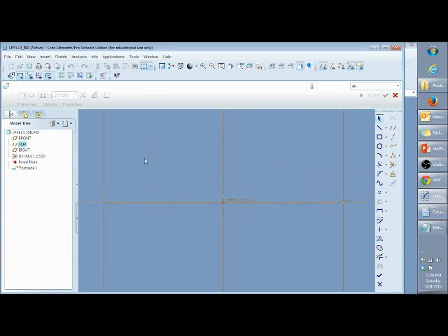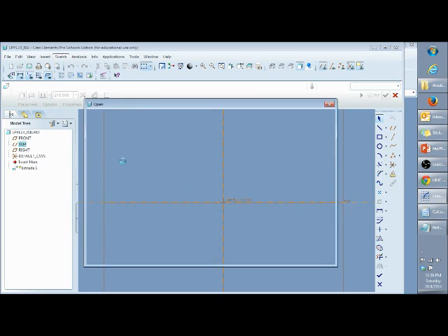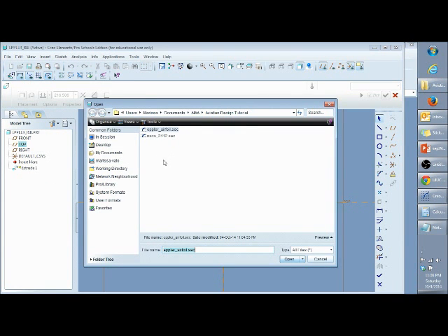Now we want to bring in that airfoil sketch that we just created into this part. To do that, you want to go to Sketch, Data from File, File System, and it'll pull up whatever your workspace is. Mine's automatically pulling this up because I had set it as my workspace directory.